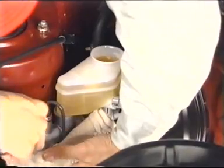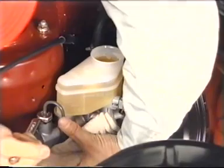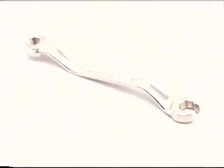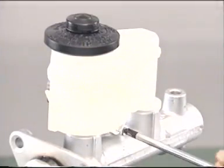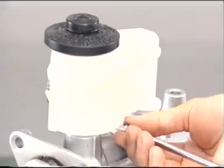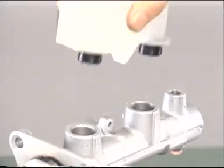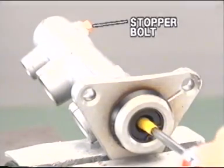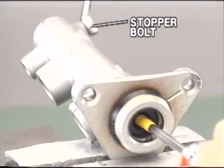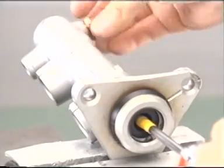Disconnect the brake tube using the SST. Do not attempt to disconnect or connect the tube with an ordinary wrench, as it will damage the hexagonal nut. Remove the reservoir tank. Next, tape the screwdriver tip. Push the pistons in all the way and remove the stopper bolt and gasket.